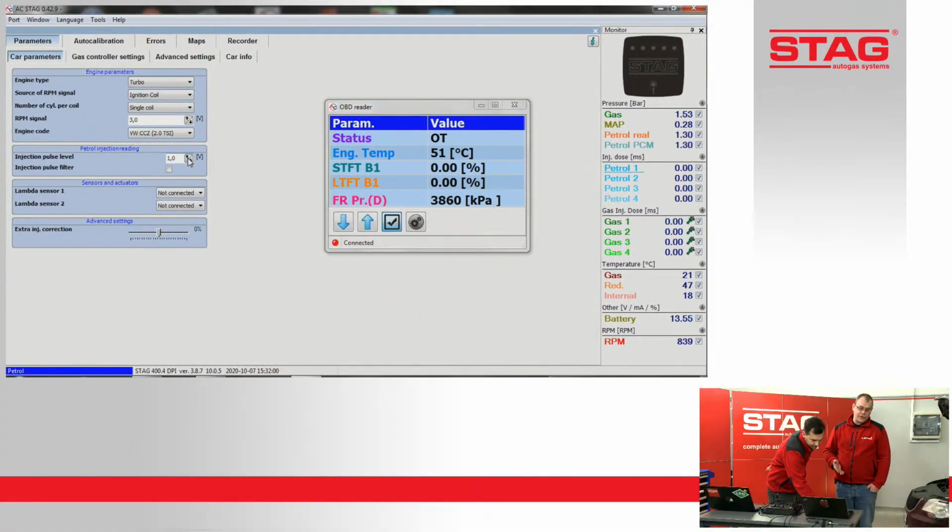It's also a common problem because some people can, by coincidence, change this parameter, and then have issues with the reading of the petrol dosage as well. Yes, exactly, and this would affect everything. Also, there would be no proper reaction on gas if the petrol injection dosage is not adjusted properly. Every car with direct injection can be different. In most cars, 3 or 5 volts would be okay, but in some cars you have to just look for the good times.